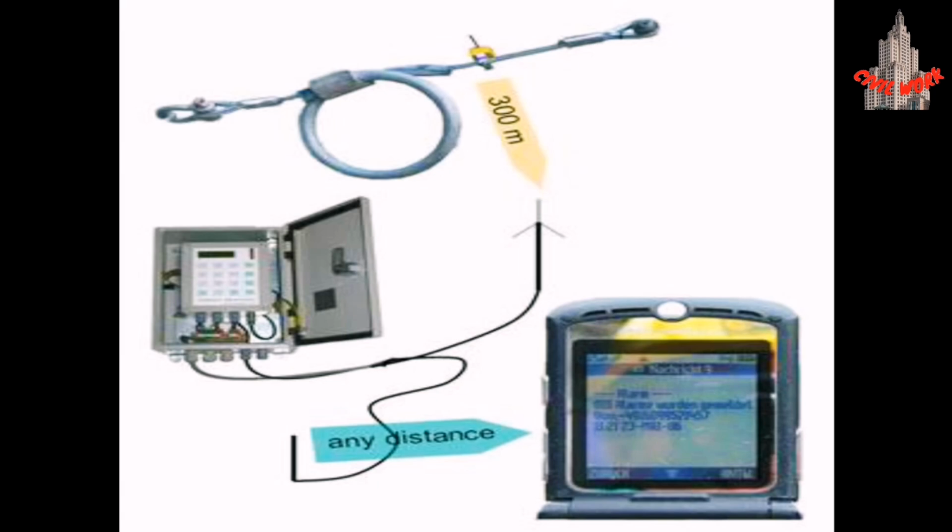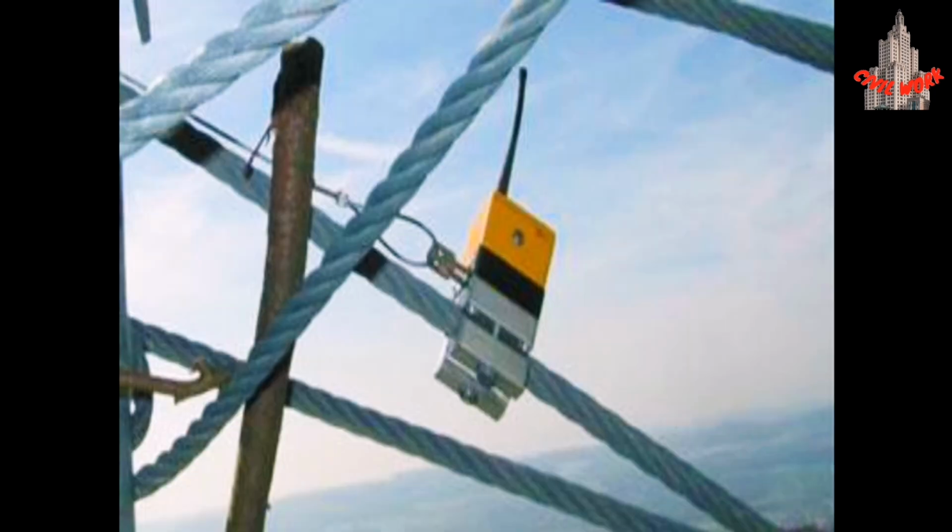We have inclinometers, which monitor the changes in the angle of the subsurface soil or the rock layers. They are typically installed in boreholes and can detect both horizontal and vertical movements. Here we have a sensor which detects the vibrations caused by the landslide and helps to inform about a great disaster initially, so that protective measures can be taken to prevent the landslide.